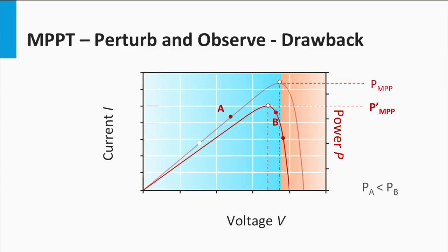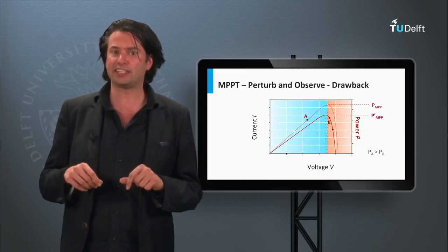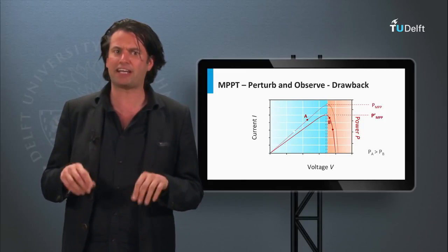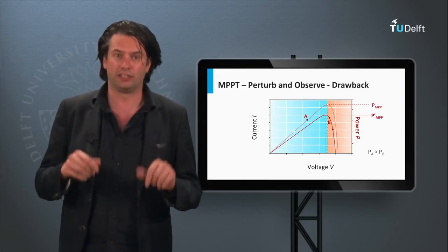This is detrimental to the speed of convergence of the P&O algorithm, which is one of the critical figures of merit in the field of maximum power point tracking techniques. Thus, drastic changes in weather conditions severely affect the algorithm's efficacy.